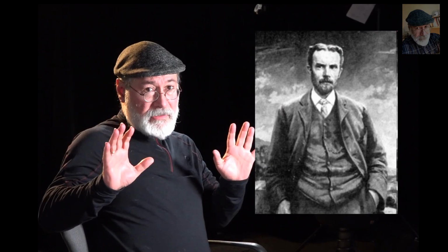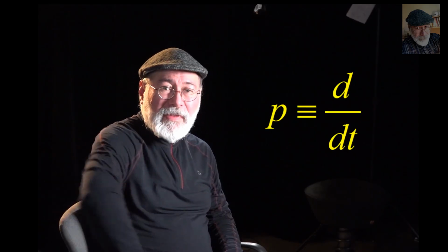So now you believe me that we need to find differential equations of circuits, huh? Over the years, I found that one of the easiest and most powerful ways of finding that differential equation for complicated circuits, not for the simple circuits that I've shown you, is by utilizing the powerful Heaviside differential P operator. Hey, don't be scared. So that differential operator is simply this one.